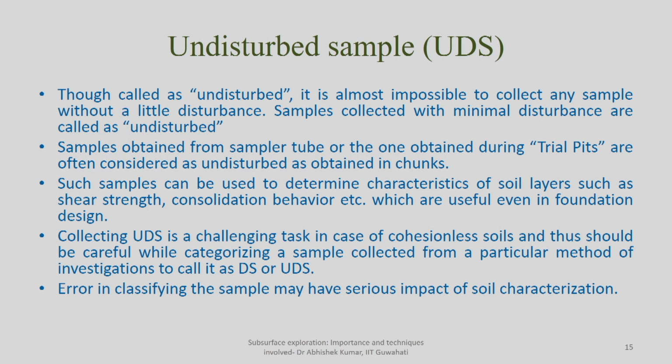Such samples are known as undisturbed soil samples, or UDS. Even if you refer to a borehole, you will be able to understand from the bore log at which particular depth you collected an undisturbed sample, whether by sampler or some other arrangement, and at what depth you collected a disturbed soil sample. A disturbed soil sample will not give you any index property, but an undisturbed soil sample will give you all those properties which are listed in the bore log in front of each depth and soil type.